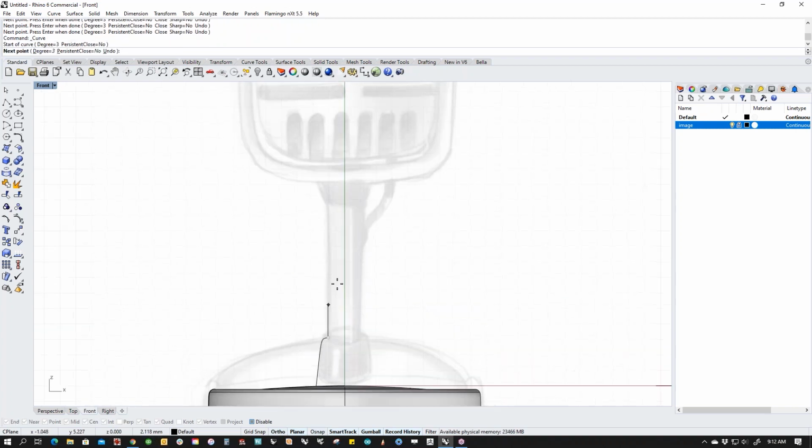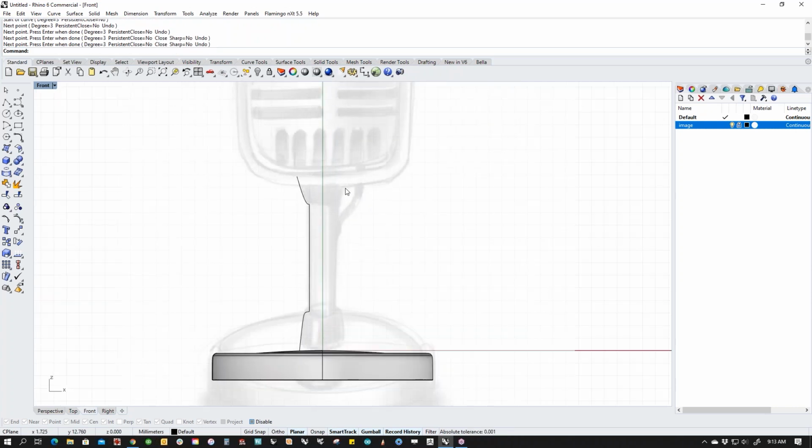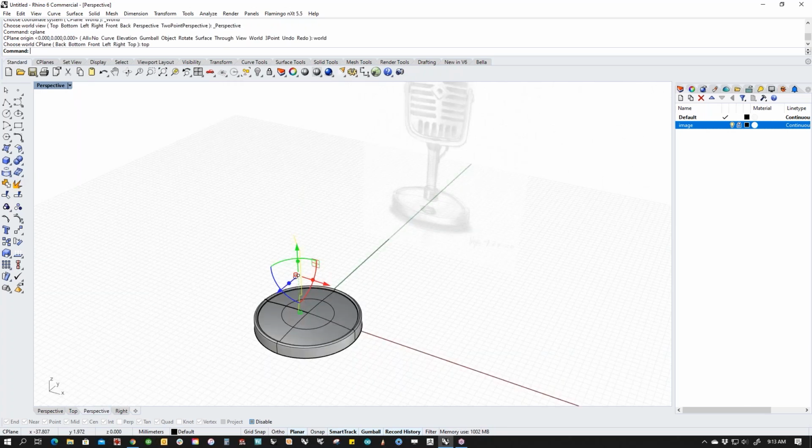And I'm going to do it as one big revolve. The other thing I'm going to talk about is the rule of 3 points to make a corner. But let's place this right about there. And then I'm going to join these up. I'm going to revolve these again, just like we did before.